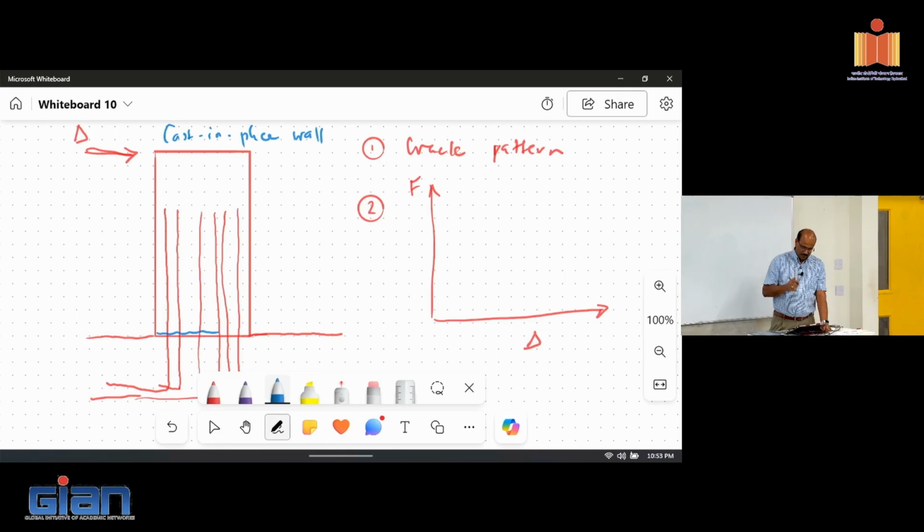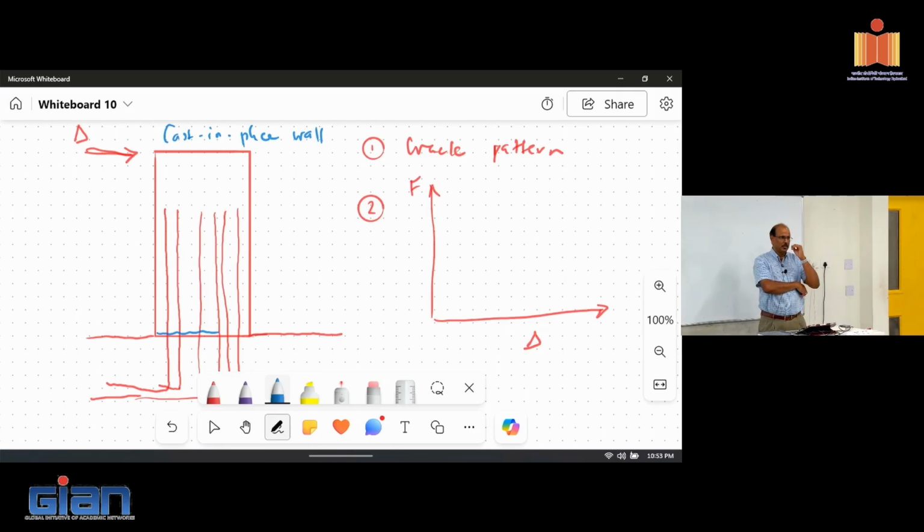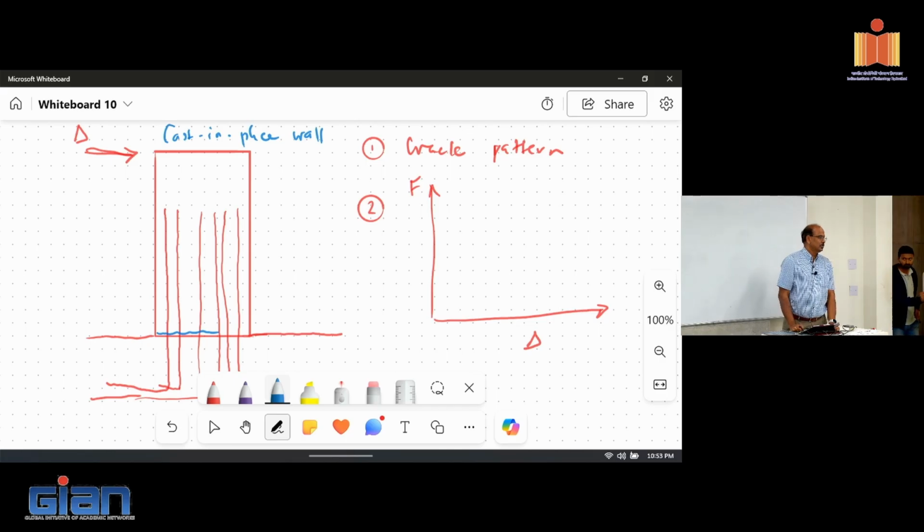So from a few very basic things you have to appreciate, initially there won't be any crack developed. As you start pushing it, wherever the flexural tension goes past the flexural tension capacity, your crack is going to start showing up. Up until then, you basically have the entire gross section participating in resisting the load, right?